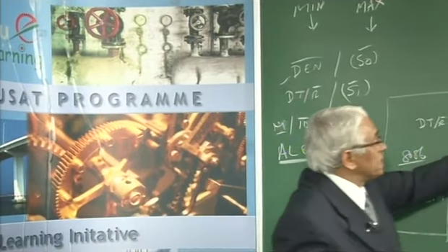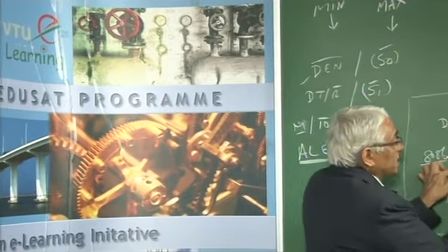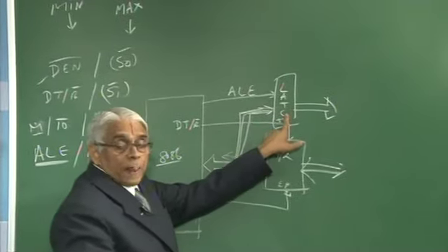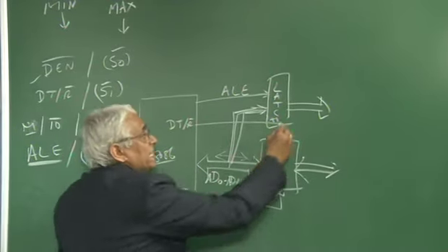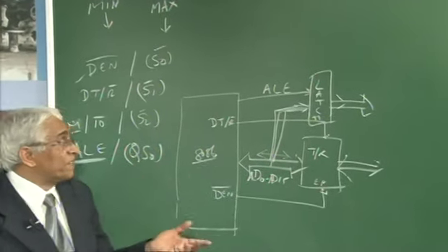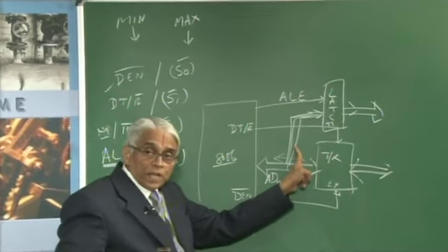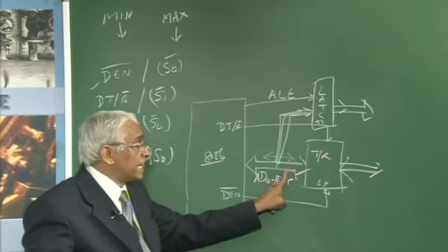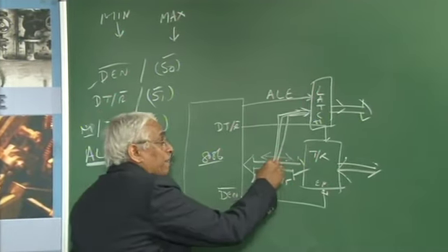It enables the latch so that whatever information is coming onto the bus is latched into it during the T1 state, and it is made available externally for the device after the T1 state, because after that period the line becomes tri-stated and then it will carry data.